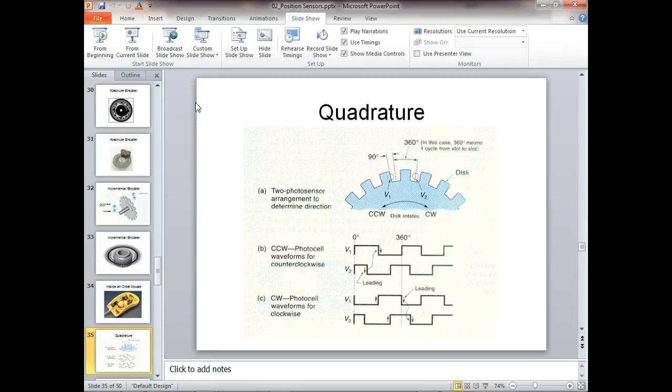Sometimes I use quadrature encoders, even if the device does not run in one direction, and I think we talked about that. So if I stop the motor and it happened to stop right here, which is probably what it does. Normally, when we reference position, we don't reference to this. And why is that? Because this is over a gap, right? Normally, what we do is we reference to this edge right here on one of these. We reference it to what we call the rising edge, the falling edge of the digital pulse.